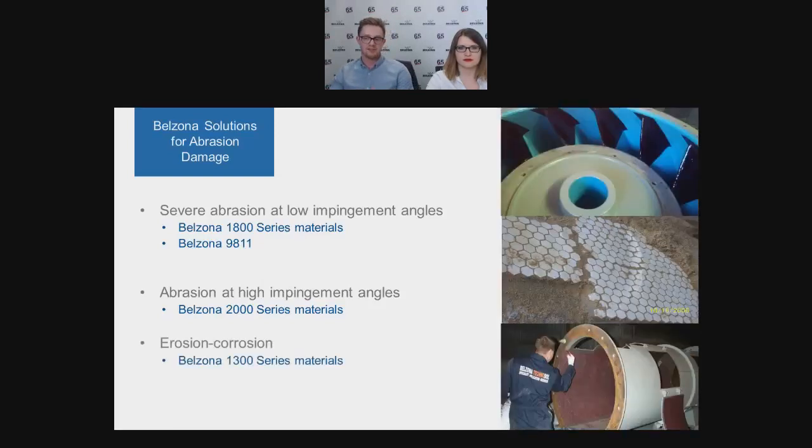And then finally, we have instances where you have what we call erosion corrosion. This is where you'd have the dual impact of some sort of mechanical abrasion or erosion and the corrosion process as well. Now, this dual acting process acts a bit like a vicious cycle. So that top layer of your steel gets corroded, much weaker. Abrasion comes along, removes that corroded material. A fresh layer then corrodes, that then abrades, and it's, as I said, a vicious cycle, constantly repeating. So that's where you get the largest amount of wear rates.